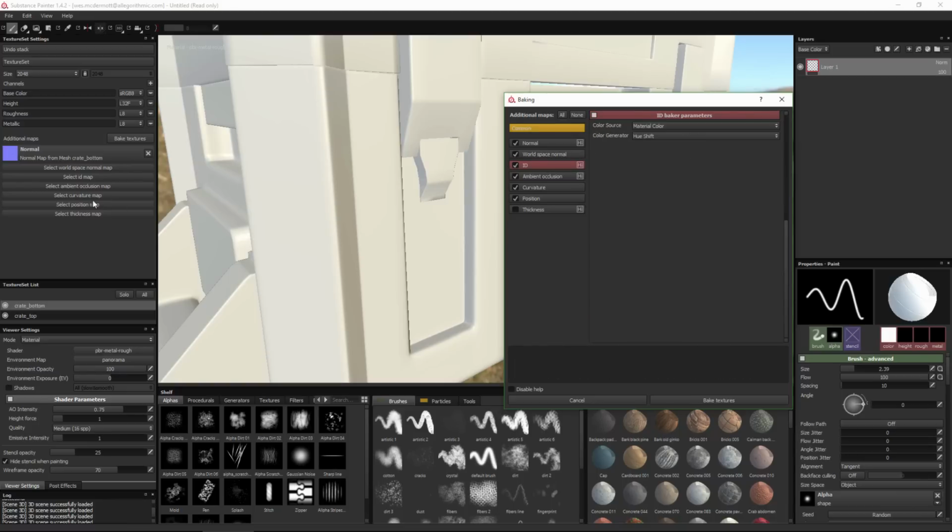Now notice here in our low resolution, we only have 2 materials, but in the high resolution, I could have many materials. So I can create several different IDs. Another option that's very handy here is this vertex color. So let's just say you use something like ZBrush and you have poly paint, and you want to be able to take that polypaint information and create an ID map out of that, you can just utilize this vertex color option. And then also here the mesh ID, it's going to take each different mesh part and use that to generate the ID.